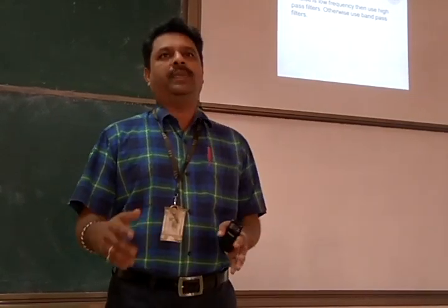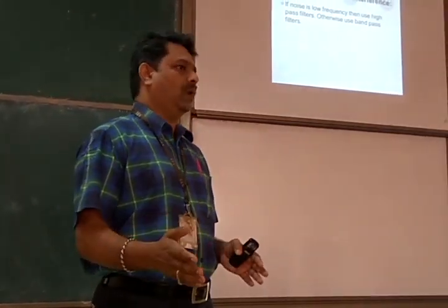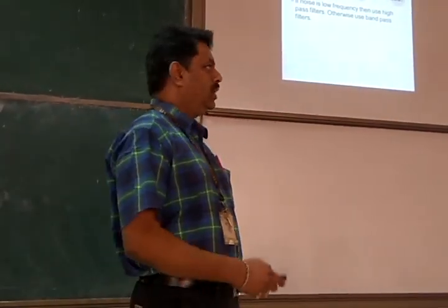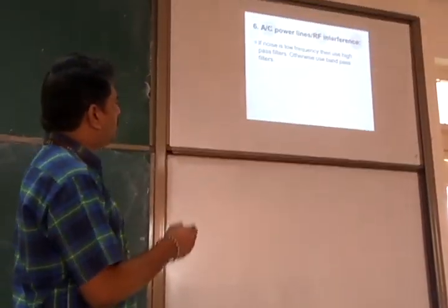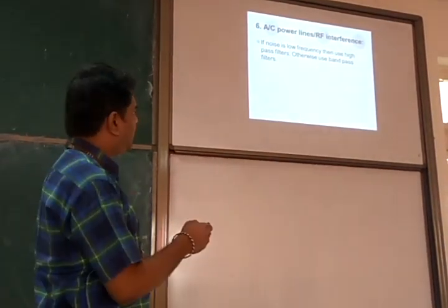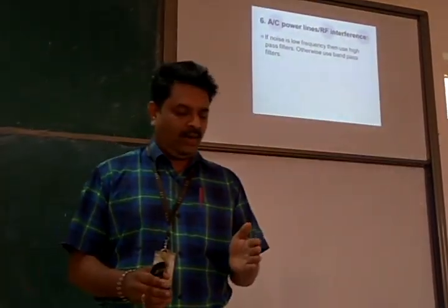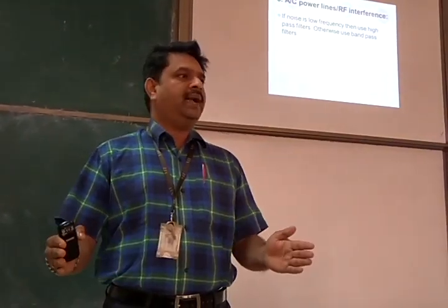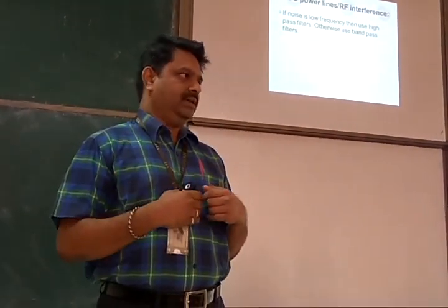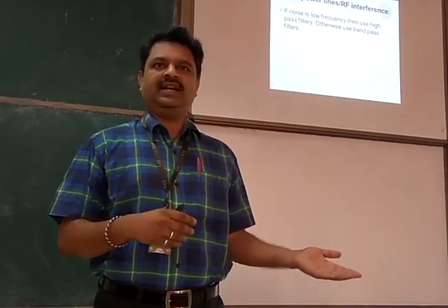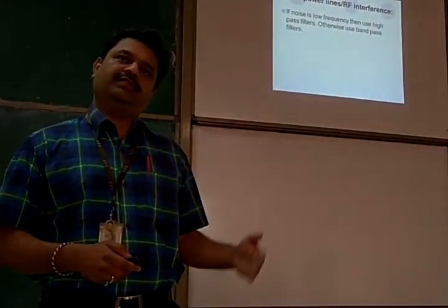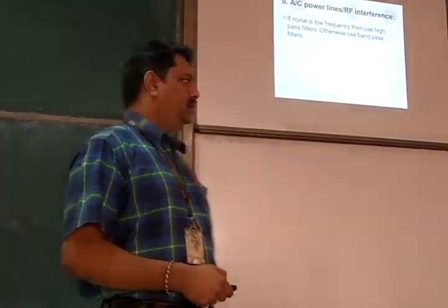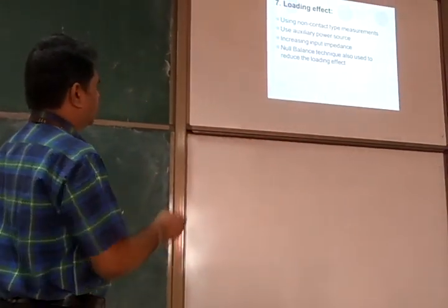This we will learn. Low pass filter, high pass filter, we will learn after CAT 1. That's a portion for CAT 1. You will understand it then if you don't know. So use appropriate filters. A band pass filter basically has a lower cutoff frequency and a higher cutoff frequency. Within that band, the signals will be allowed inside. Anything other than that will not be allowed. So we use the kind of frequency filters, take the appropriate signal and remove the other signals.